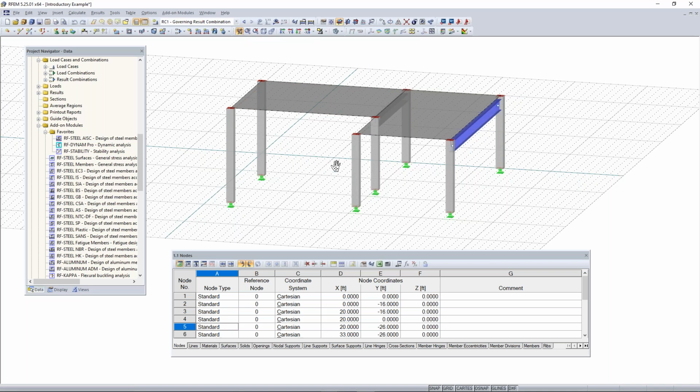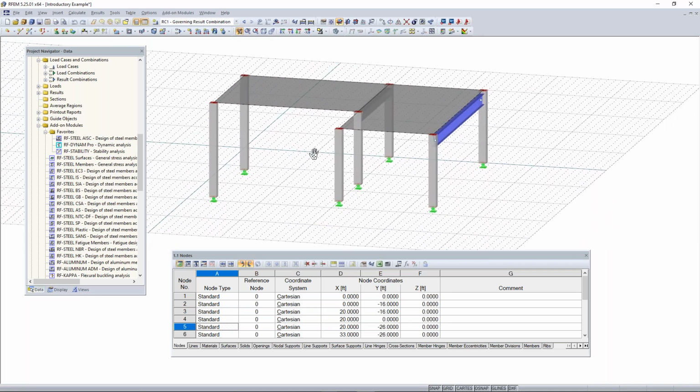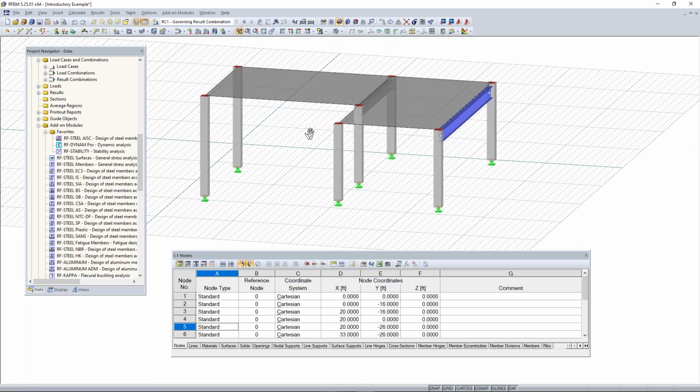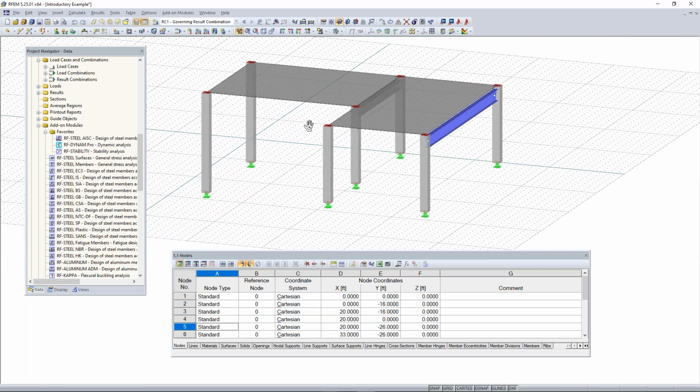You can click on that and then you can left click to move. You can also hold Shift, and then you can zoom in and out with left click, and you can hold Control and rotate the model. So that's pretty handy. You can also do all of this with the arrow keys on your keyboard, and they perform the same function.